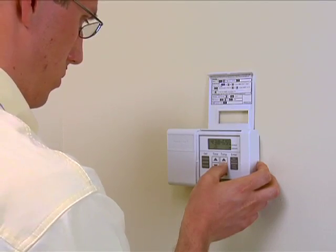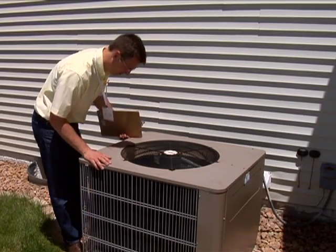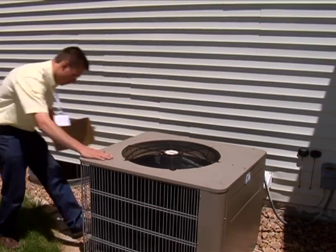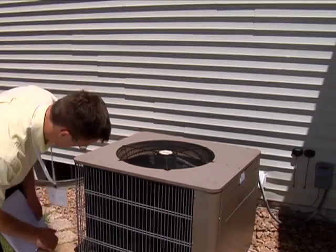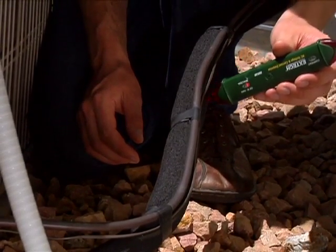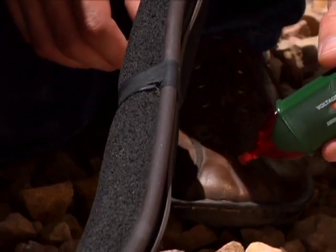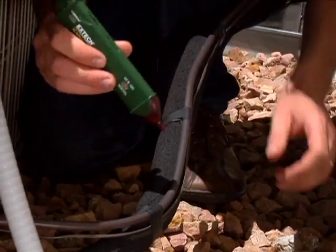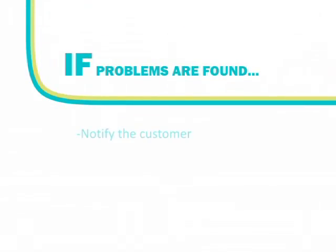Go to the air conditioner unit and perform a visual inspection of the unit. Look to ensure the coils are free of debris and vegetation, and that the unit appears to be generally in good condition. Use a non-contact voltage detection device along the control wire to confirm the signal to operate is being sent to the unit. If problems are found, the customer should be notified of the potential need for service, and you should decline the installation.